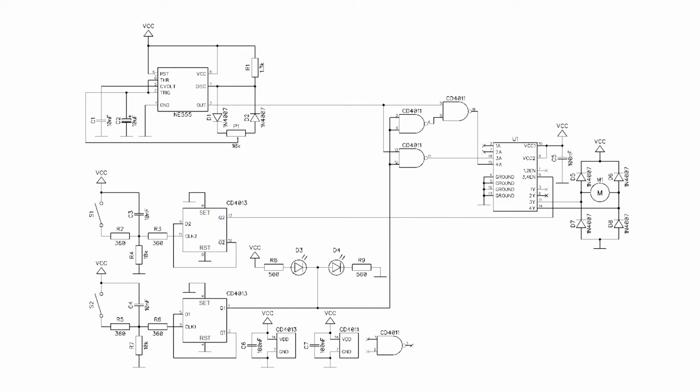Systems with resistors and capacitors on the CLK inputs are used to eliminate the so-called contact vibrations. In practice, pressing the switch generates vibrations, which is revealed by fast switching on several times until the mechanism has stabilized. LEDs marked as D3 and D4, depending on the state at the output Q1, indicate the direction of rotation.